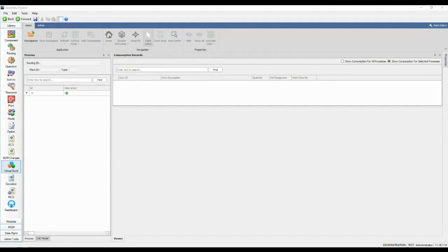Inside the converted CAD file format, there are two choices. One, as you can see, being PRC, and that is our default, and one being HSF. The difference between the two is PRC will give higher level of quality with a little more detail. HSF is geared to be ultra lightweight, so you get increased speed and performance at the sacrifice of some quality.